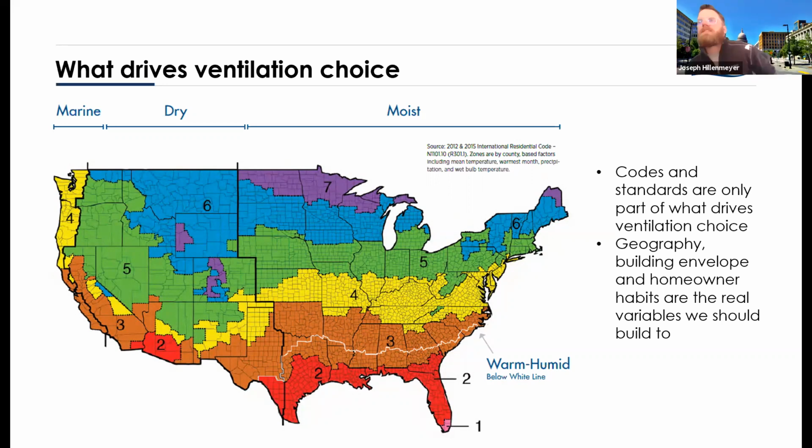I think the number one choice you would want to have in any home, if you have a forced air system, let me say that first of all, would be MERV 13 whole house filtration. That's literally removing the damaging particulate in the air that we know impacts health, not just in the short term, but in the long term. There is no question that they're bad for us. If we don't filter them with the systems in the home, then we're filtering them with our lungs, and that's where they start to cause problems.